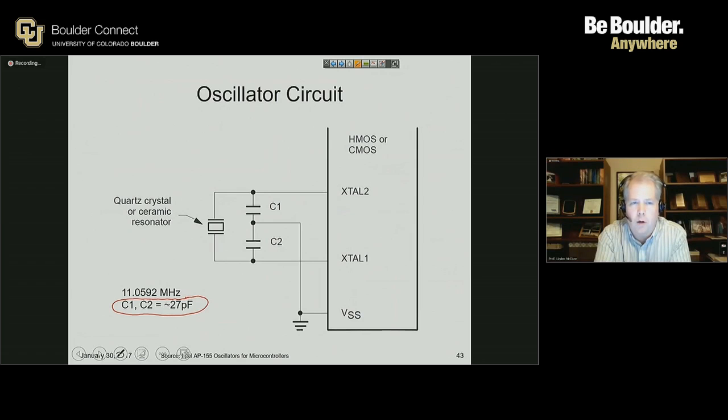The oscilloscope probes that we have in our lab are passive probes. What's a characteristic of a passive probe? They have a capacitance in them. Absolutely, probe capacitance. Does anybody have a feel for what the probe capacitance of a passive probe might be, in picofarads? Yep, maybe 10 to 50 picofarads would be a common range.